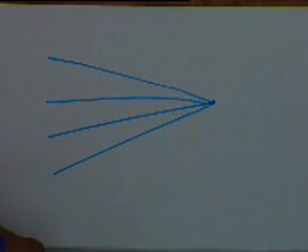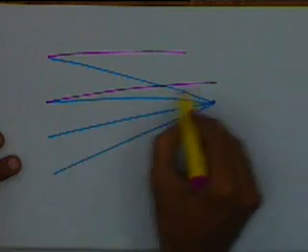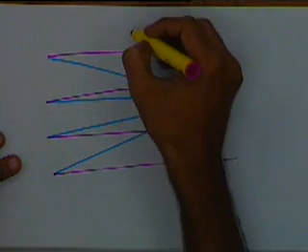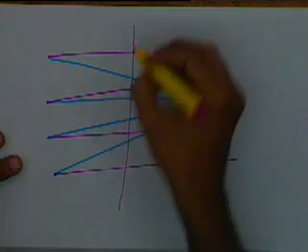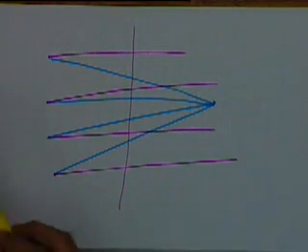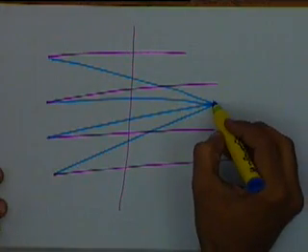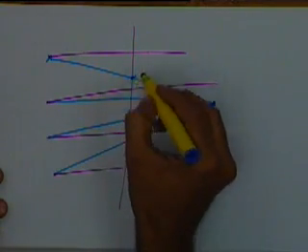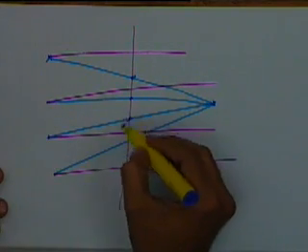Earlier, when we were talking of the orthographic projection, the projecting lines were all parallel, and we had a projecting plane like this. So this is the projecting plane, and the projecting lines, instead of being parallel, are focused on the eye. In that case, a point here will get transformed to this point, and this one will get transformed here, and so on.